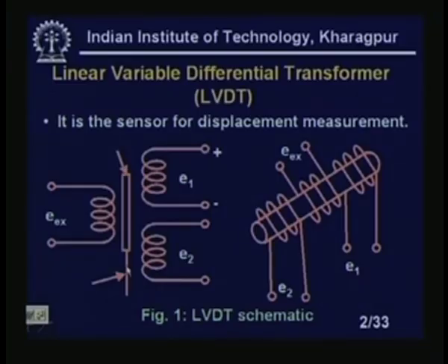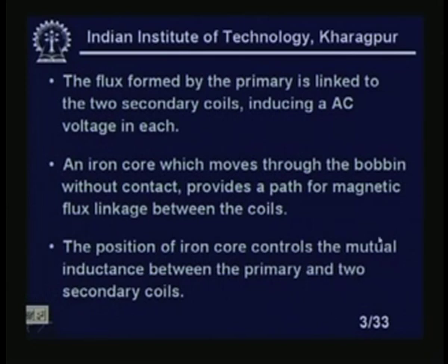Welcome back to the classroom again. So, we have seen the construction of an LVDT and how it works. This core will move up and down, and I will get different mutual inductance, the voltage will also change, and there will be a phase difference between the input and output. That is what we have written in a nice way.